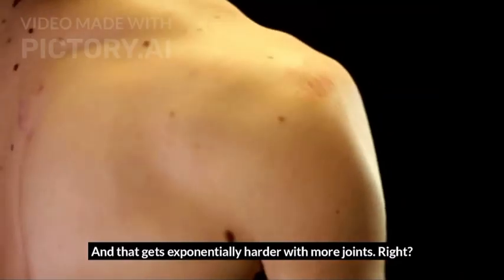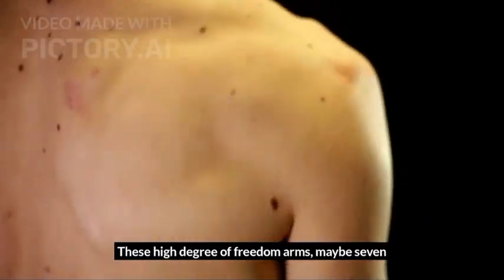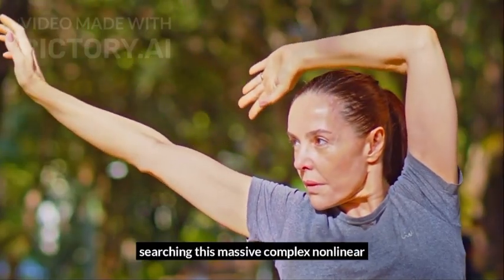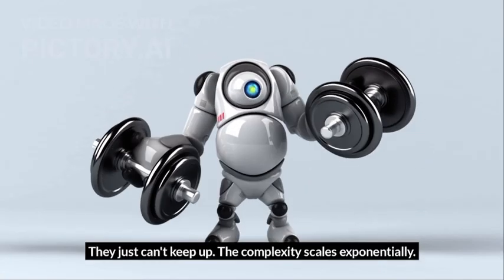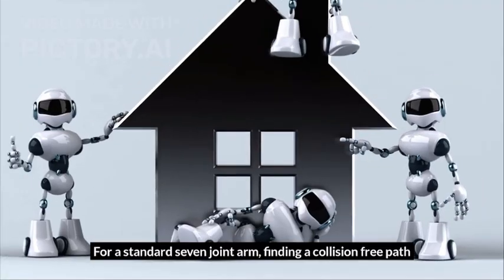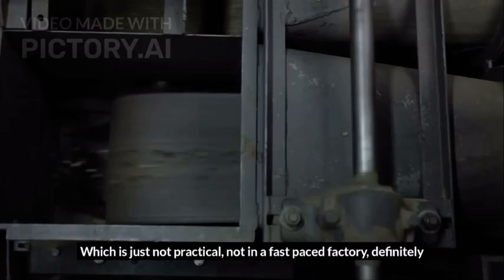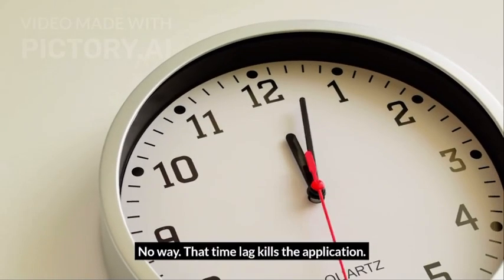And that gets exponentially harder with more joints, right? These high degree of freedom arms, maybe 7 joints like a human arm. Exactly. The number of possible configurations just explodes. You're searching this massive, complex, nonlinear space. And classical methods, like trying every possibility, they just can't keep up. The complexity scales exponentially, something like O(K^N), where N is the number of joints. For a standard 7-joint arm, finding a collision-free path could take minutes, maybe even hours with older methods. Which is just not practical. Not in a fast-paced factory, definitely not in surgery. No way. That time lag kills the application.